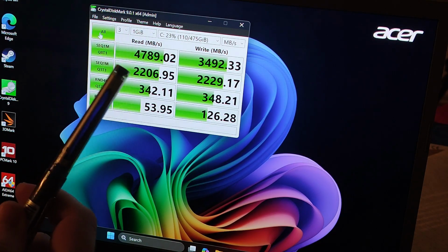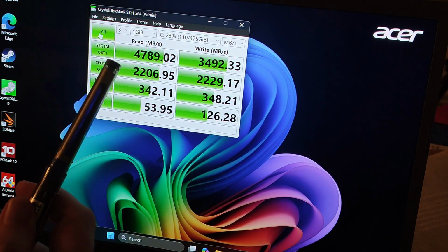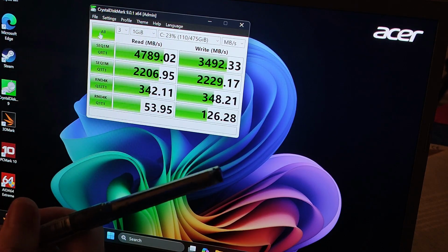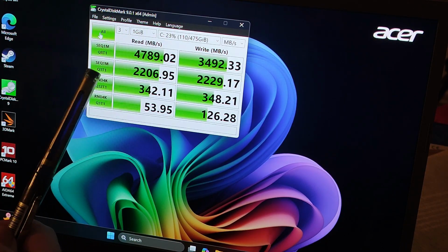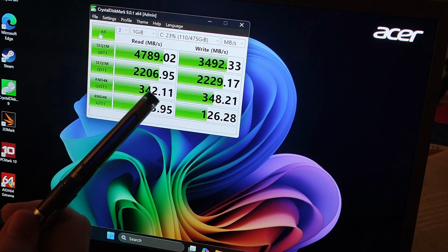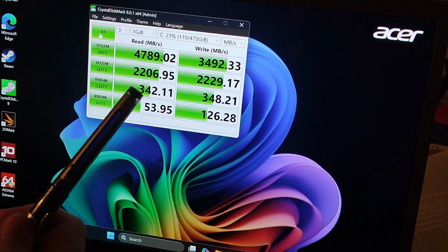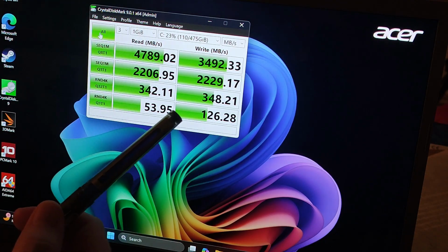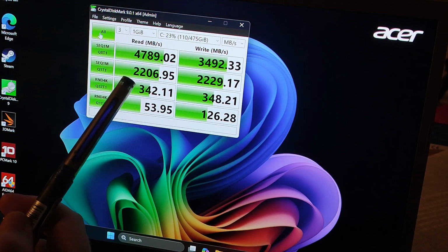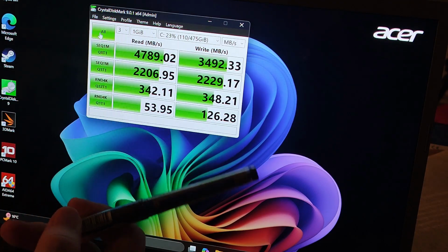And to get many terabytes written tolerance, or mean time to failure, so to speak, you want a high capacity drive, because you can usually write a lot more data to, let's say, a 2 terabyte drive before it fails than to a half a terabyte drive before it fails, because you have more memory cells.